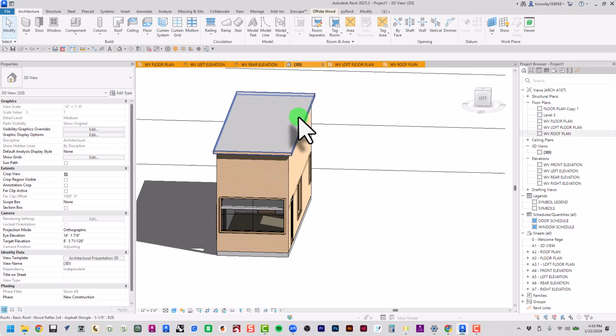And the reason for it is because it has a lot of potential for drainage issues and pooling, right? Water will just collect on this roof, and then the asphalt shingles and the finish and the structure will start to sag and be severed, and water will fall through the drywall or the wood planks that we have and enter into the interior and cause a whole mess of issues. So what we want to do is add a slope.